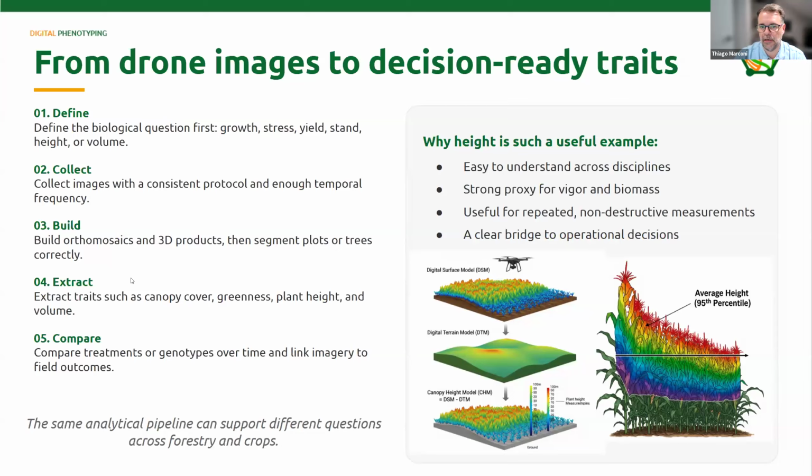Then we can design and build a protocol for image data collection. Very important, as Igor was mentioning, is a way to measure very accurately: use RTK drones and GCPs in your field, so you can really make sure that you're collecting data consistently.